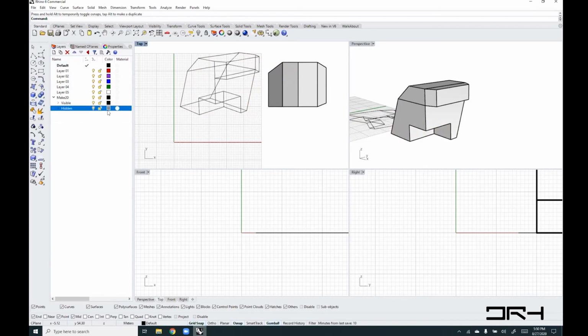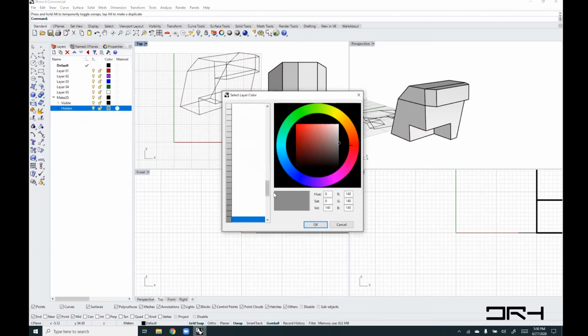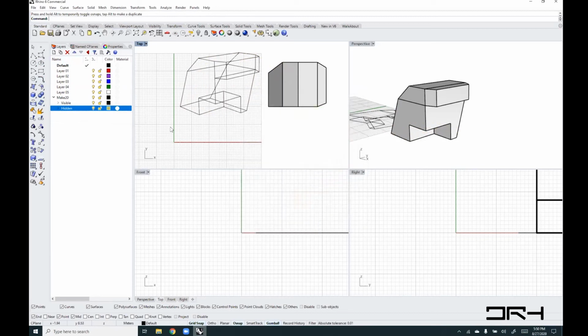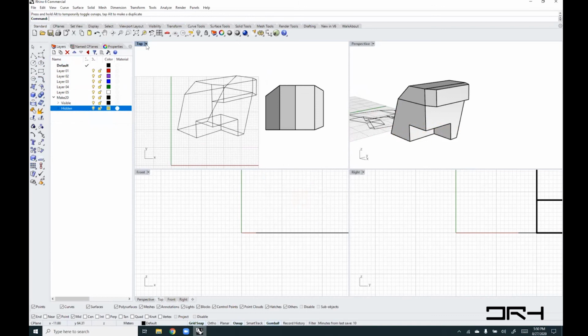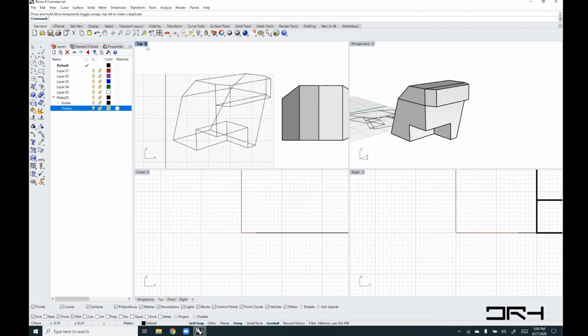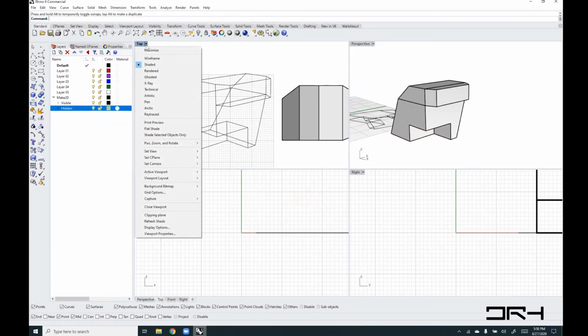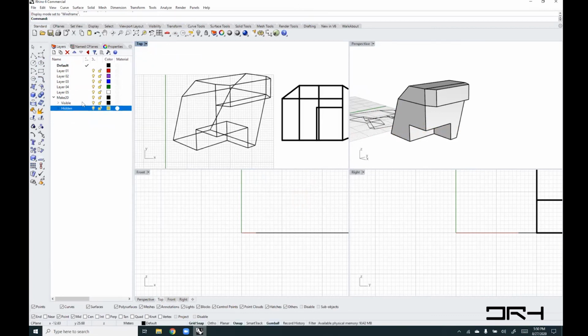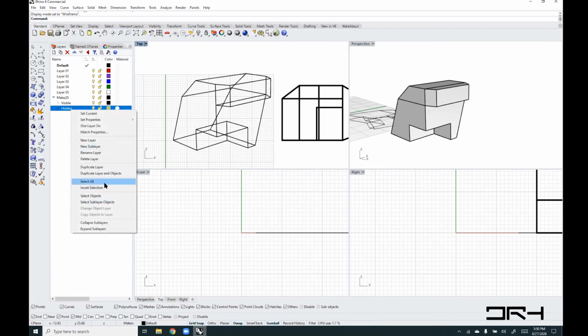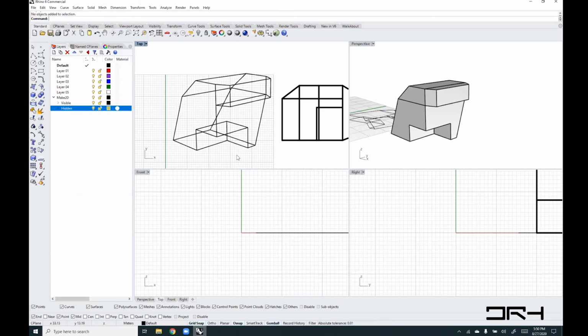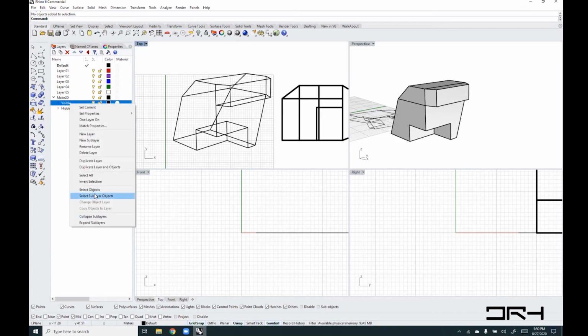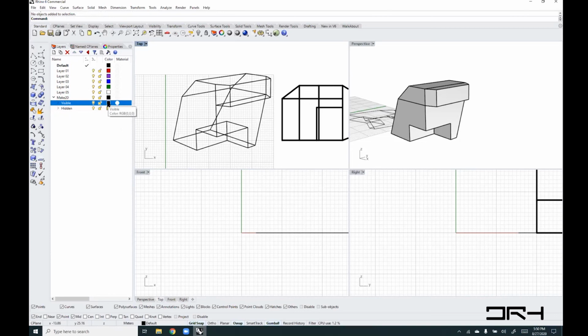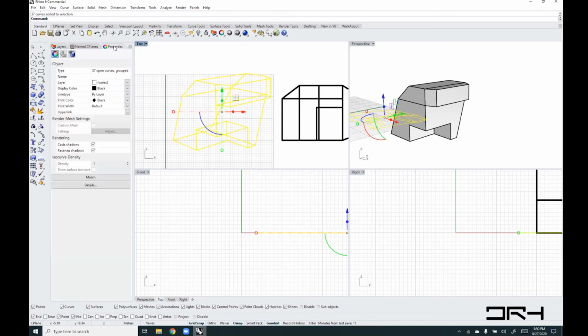These are the hidden lines. By default, they are colored gray. Let me change them to a color that is a little more distinguishable. Okay, say okay. So in top view, the layer is shaded, wireframe, select objects. Is it locked? Okay, visible. Select objects, something is happening. It's not changing the color there, because, why? Let me select that and see what the property is.